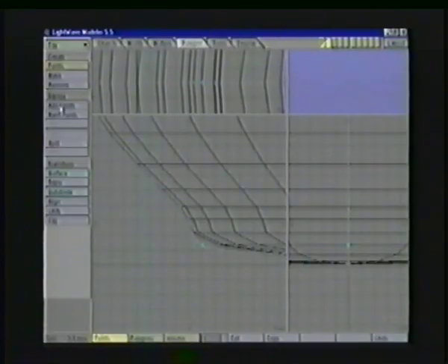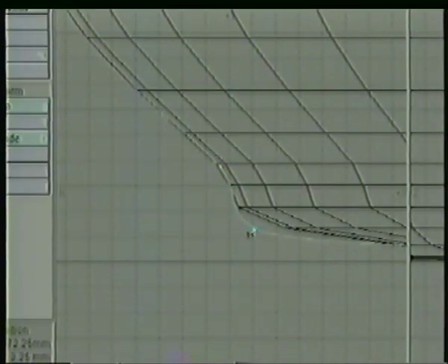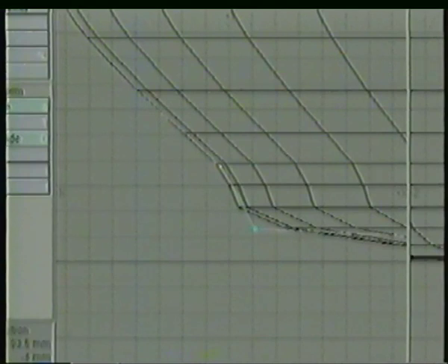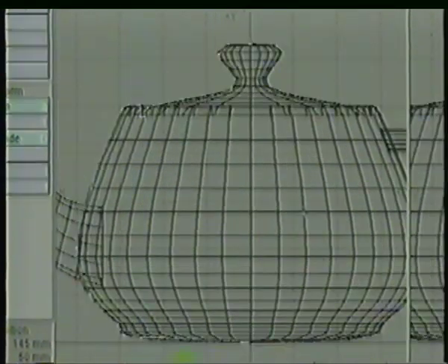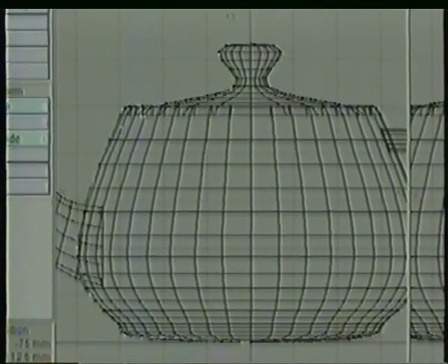So I'm going to go to Polygon panel and use the Add Points tool. My cursor becomes a little arrow with the word 2 next to it. And I'm going to click directly on top of that point. That will add the point directly on top of the other point. You can see how the curve snapped to a corner right there at the bottom, right at the junction of those 2 points. Let's hit A to zoom back out again, and then the period key to zoom back in a little bit.